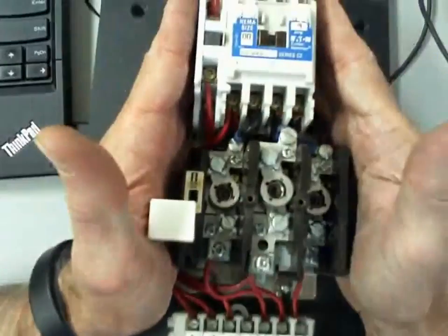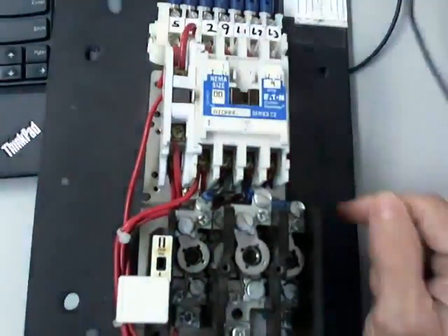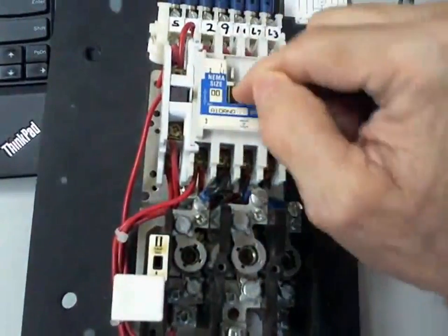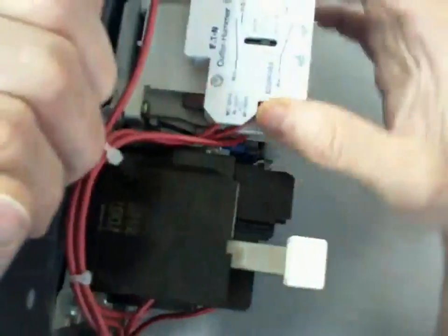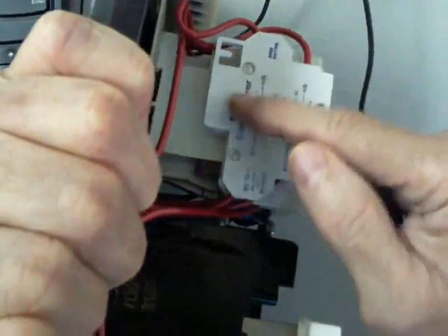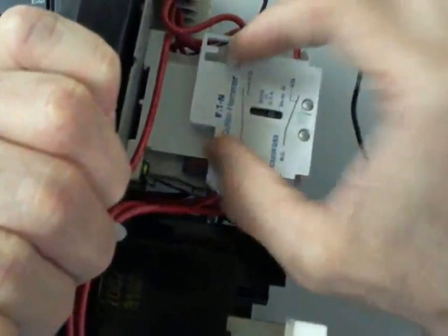So this is a magnetic motor starter. Here's the auxiliary contact strung on the side. Here you can actually see this. Here's the force button right here, or the manual override. Okay, I think this book calls these press to test. Normally when we're in the field, they're going to call it an override. And you can actually see the operator. So you can see it working right here. So we can come in, and these are, somebody help me out. Yeah, these are not screws, but normally these are screws right here that you could actually put more.